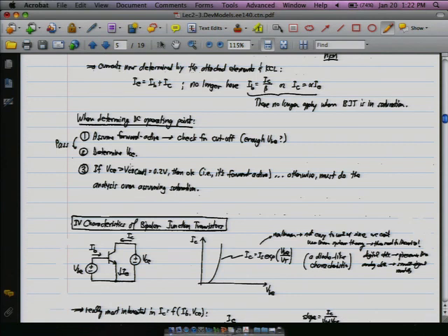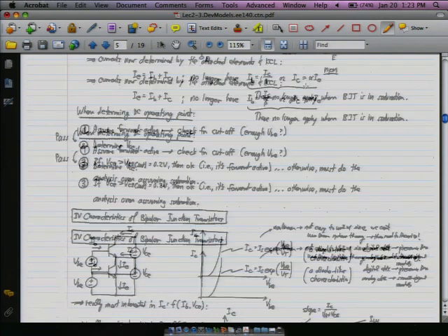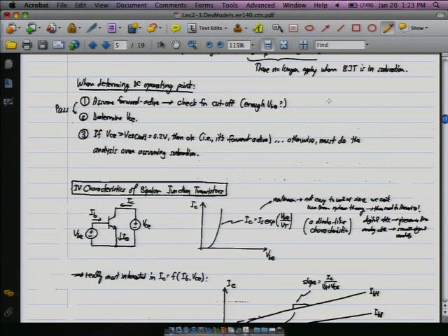just because that's our most common configuration. So it's not anything major. If you just use a KVL, it's exactly the same thing, but it's just referenced differently. So usually we have this expression here that's called VCE sat, and you need at least this value of VCE, so this voltage here between the collector and the emitter, to make sure that you're in forward active.